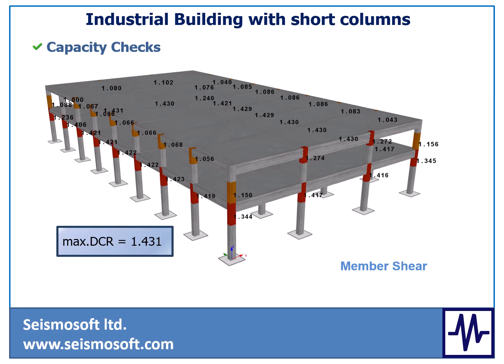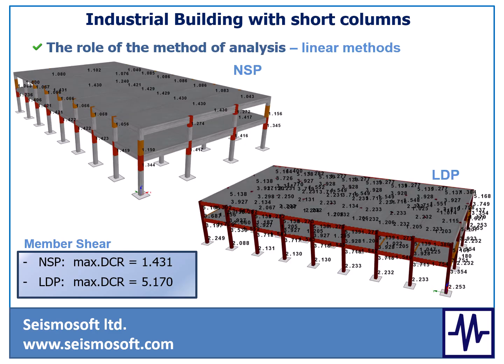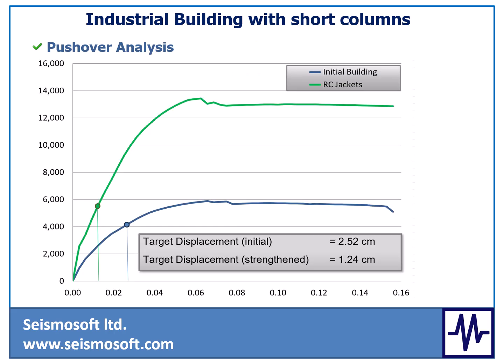The capacity checks will be carried out, and the effect of the infilled walls will be studied. The role of the selected method of analysis, linear or nonlinear, will be investigated and it will be demonstrated why the nonlinear methods are more appropriate for the analysis and assessment of existing reinforced concrete buildings. Finally, the building will be strengthened with 2 different methods and the structural response, with and without the strengthening, will be compared.